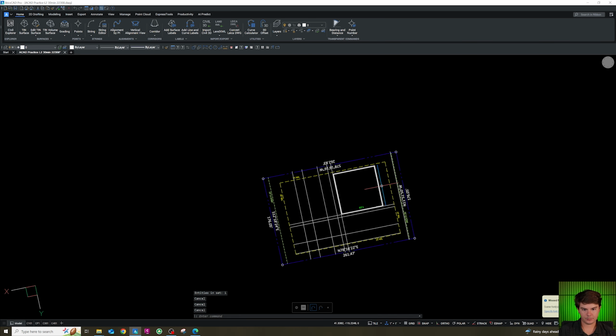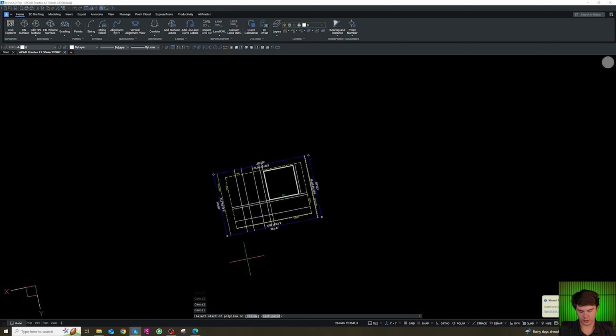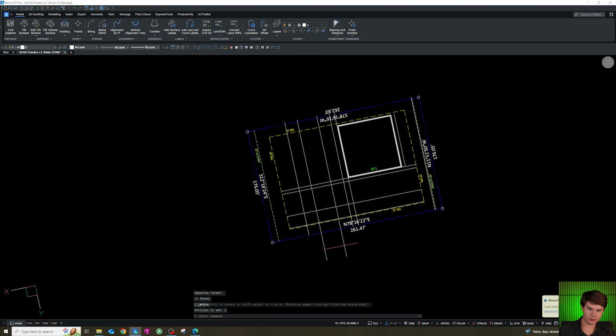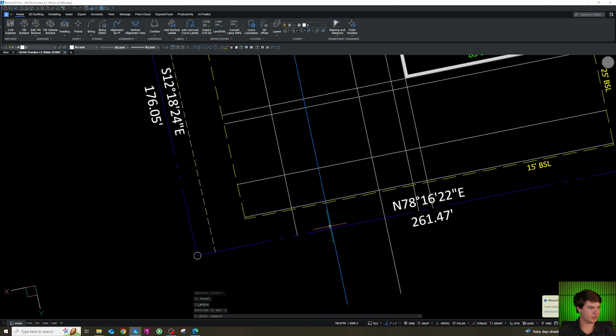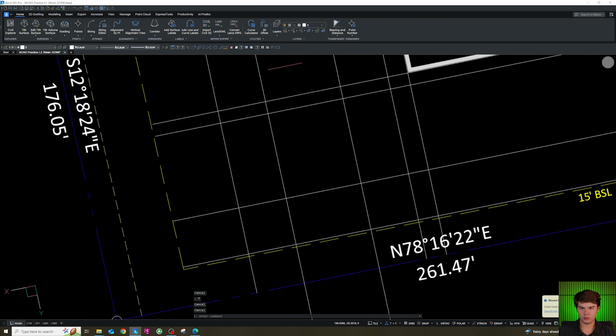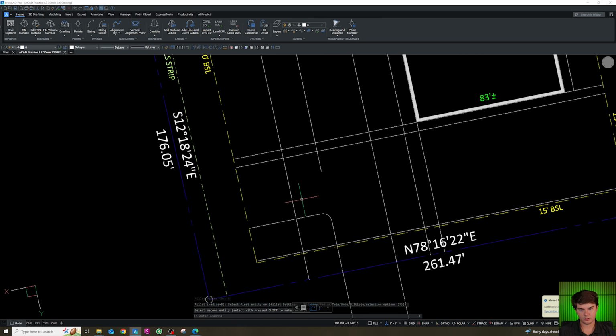Delete that. We can go ahead and put our parking in here. I know that this is our drive aisle here, so I'm just going to go ahead and connect it to the imaginary road. And I know our parking is going to want to start along here, so I'm going to do the BB command so our line doesn't disappear. This is a radius of 5 up here, and then a radius of 0. Turn that away.